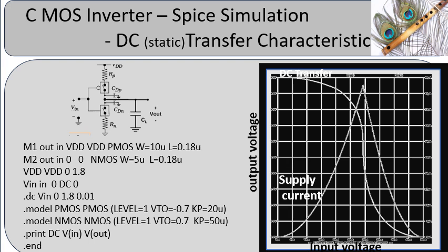From the transfer characteristics, we observe that in the flat regions of the DC transfer curve, the inverter output is stable at either logic high or low states. In the transition region, both NMOS and PMOS are conducting and the output is in a rapid transition state. The DC transfer characteristic helps designers to analyze robustness of logic levels and generate noise margins of the inverter.